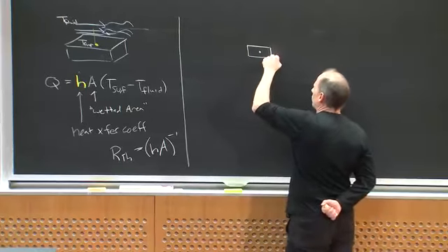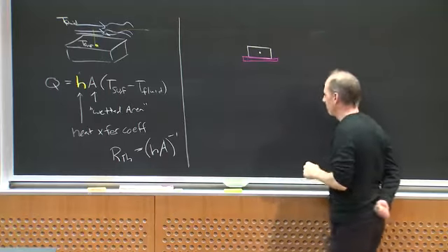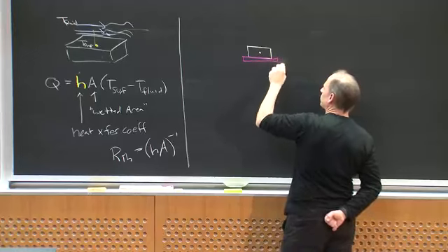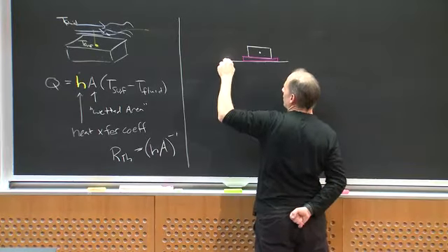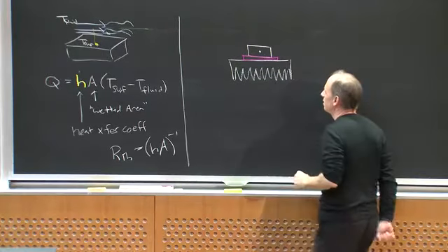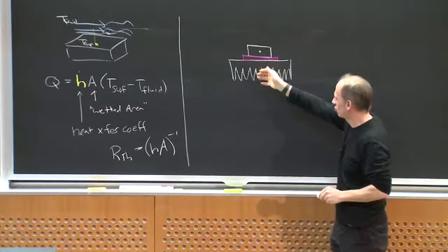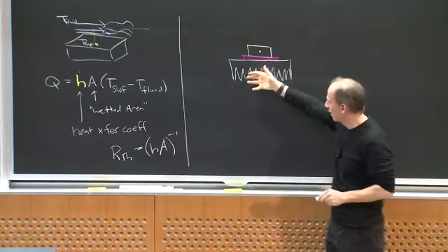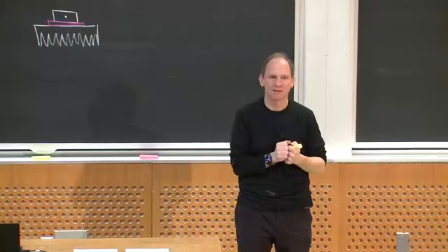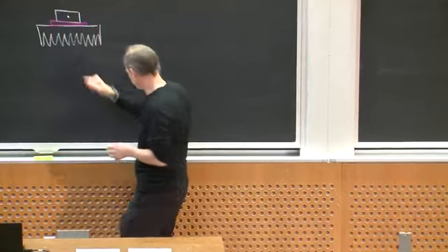And here, when I connect this device, I'm going to have some interface. What is that interface? I'll talk about that in a second, but that's going to be between the device and then maybe a heat sink. And maybe this heat sink has a bunch of fins that's designed to help me cool this thing. So the heat's going to come from the device through this interface into the heat sink, and then maybe the heat sink's transferring it off by convection past the heat sink out into space around it, and then I forget about the heat, right? It's just going out somewhere. Well, what is this interface?